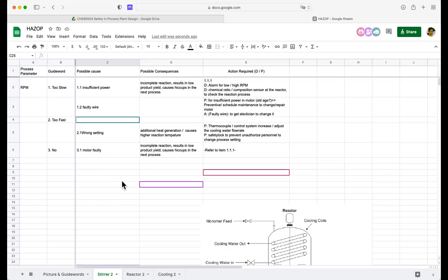Because this is how we look at what could go wrong. Then we want to prioritize. We start to say, okay, this is important, we will have to do this first. This is not important, this one may happen, may not happen, then we can put it aside first. But when anything goes wrong, you can always refer back to this handbook, the HAZOP handbook that you and your team created. Any questions so far?